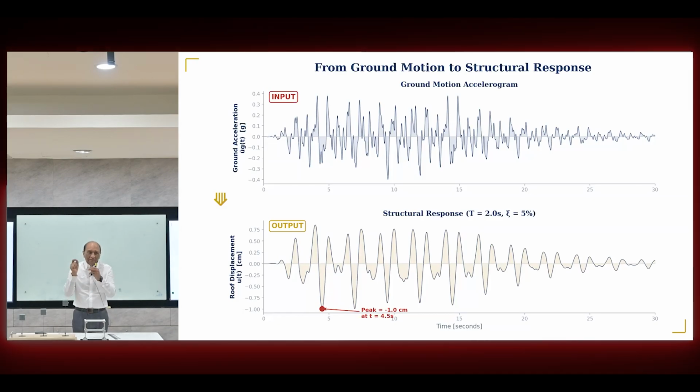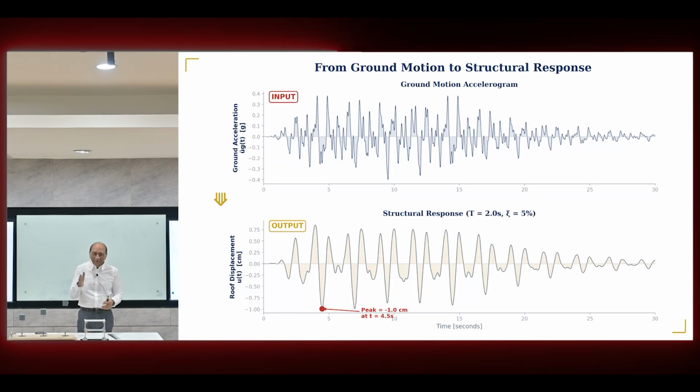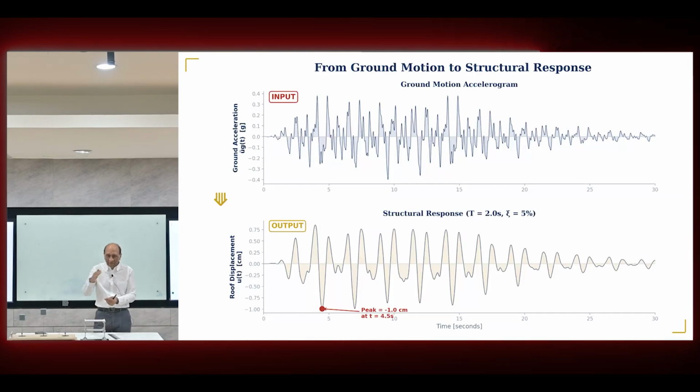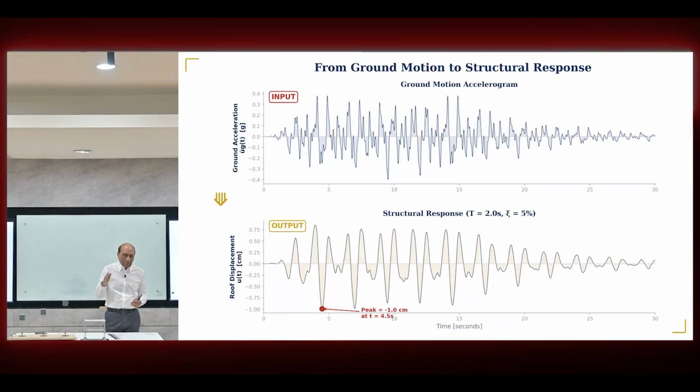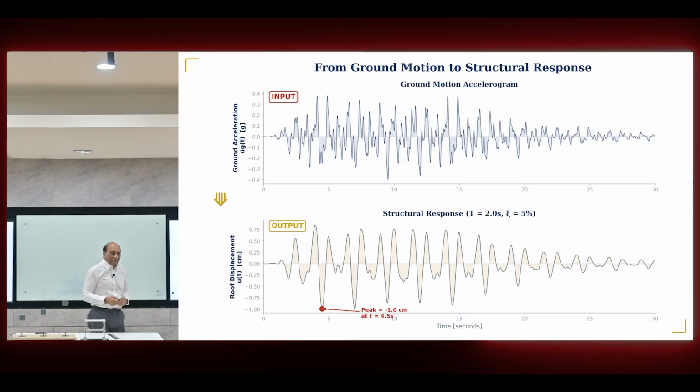And the good thing is that the bending moments and shear forces will be corresponding to that displacement at that time in that part of the structure. And this will be cumulative. If the structure has already moved a little bit and you apply the ground motion, it will start from that and move forward. So it's not isolated. The structure's natural response and damping and whatever it is will be accounted for in that analysis. So that's the advantage of running linear time history analysis without significantly more effort.